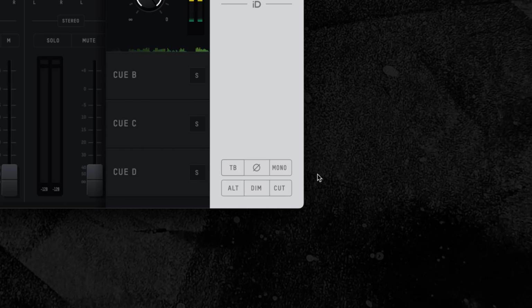To assign these function buttons, right-click on the desired monitoring function and a drop-down menu will appear with a choice of F1, F2, or none. Once F1 or F2 is selected, the assigned hardware function button on the ID48 unit will light up when its assigned function is active. Additionally, when hovering the mouse over a monitoring function, if it is assigned to a hardware button, this will be reflected in a text pop-up showing either F1 or F2.